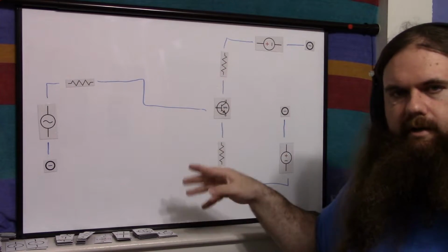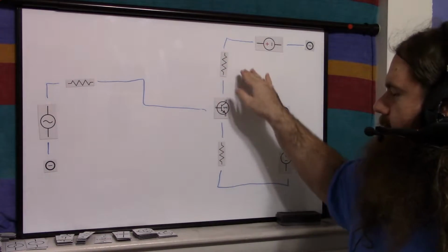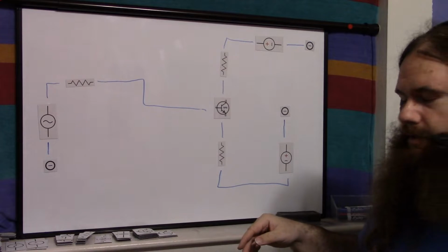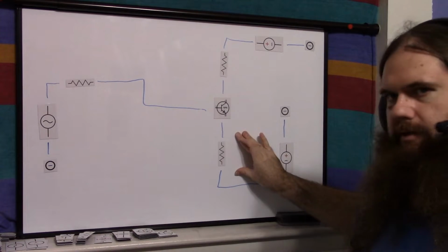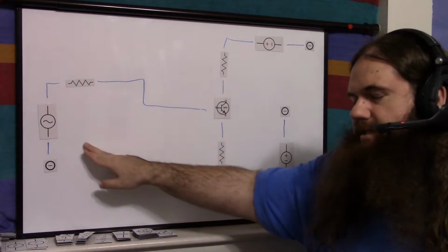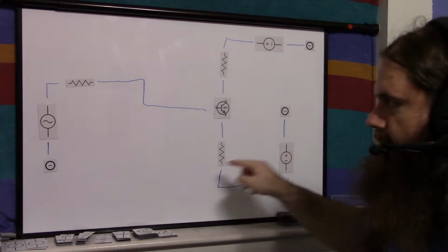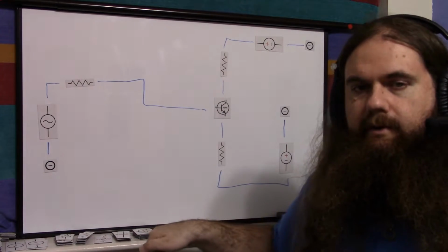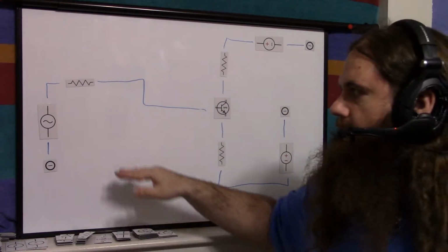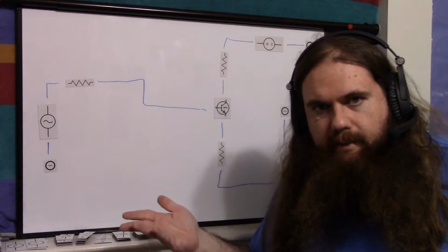And so Ohm's law and currents and all that other stuff determines what the voltage drops on the resistors are, but the point is, there's always going to be a voltage drop here, as long as the signal doesn't go too crazy. If you have a 5 volt power supply here and your signal goes to negative 6 volts, then it's all going to stop again. But the same thing would happen in the common emitter amplifier.